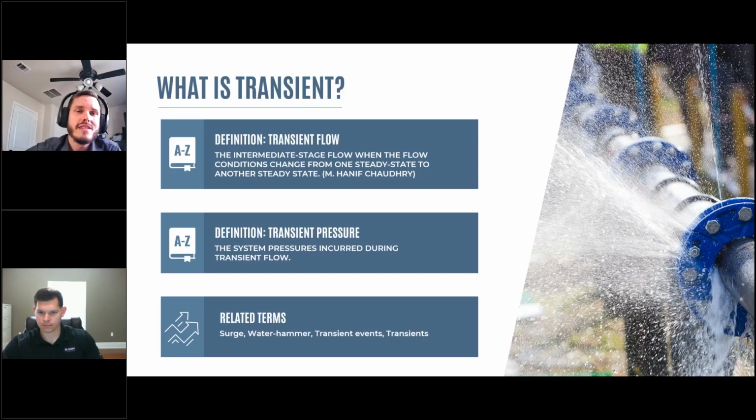Because of how fast water hammer occurs, it often goes unnoticed, and because it's not understood, it's only sometimes suspected after a failure occurs. We tend to suspect malfunctioning equipment such as stuck air vacuum valves, relief valve, check valve, when actually the wave passed by the valve much faster than the valve could react. We don't have widely used equipment installed to properly detect transients in our piping systems yet.